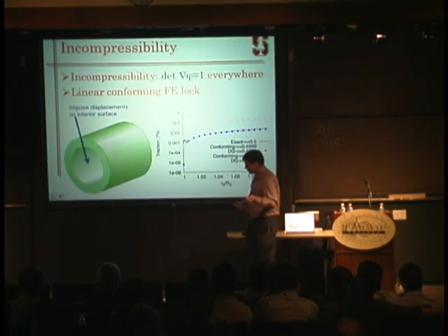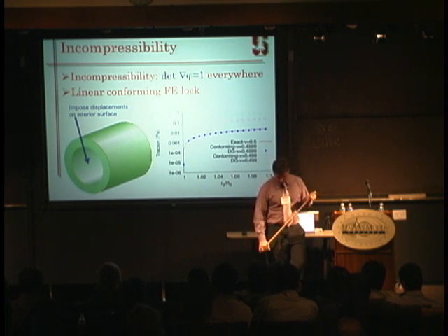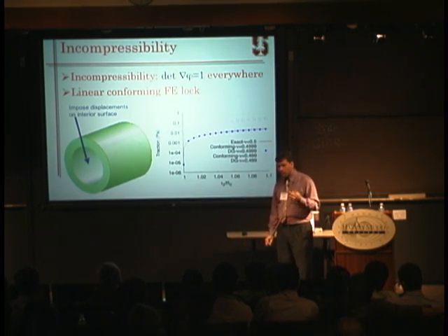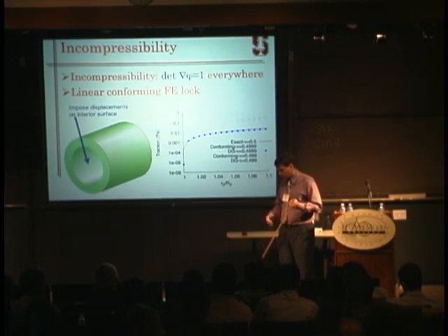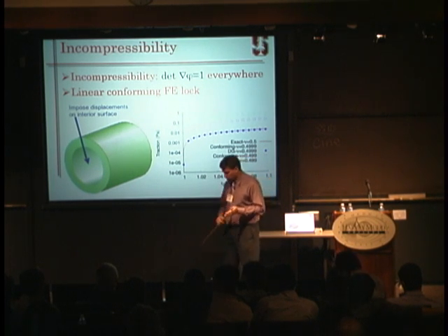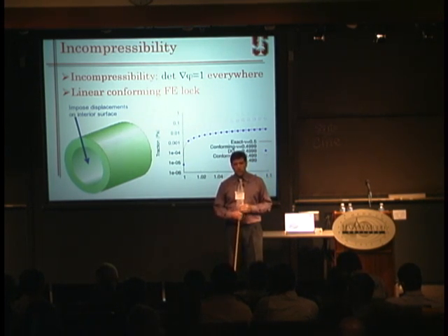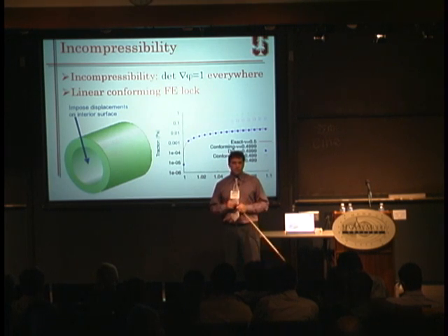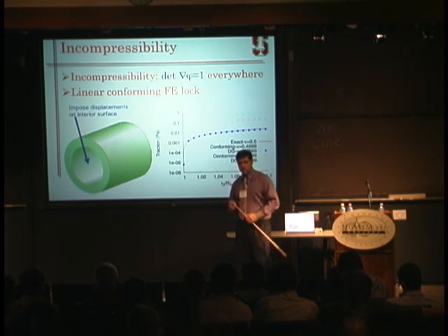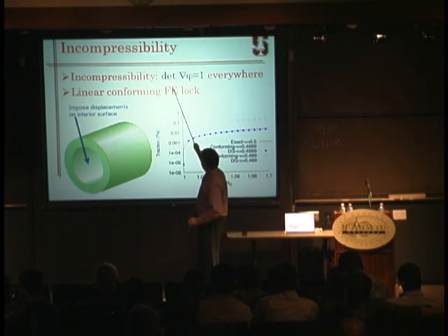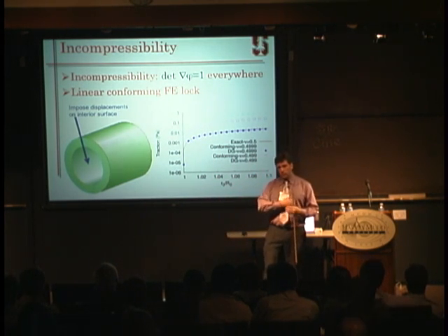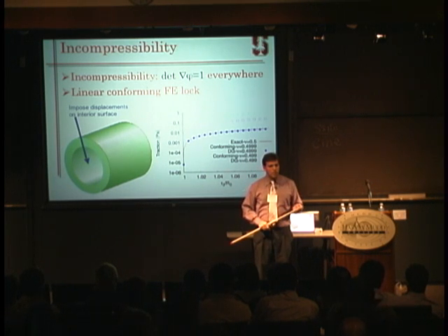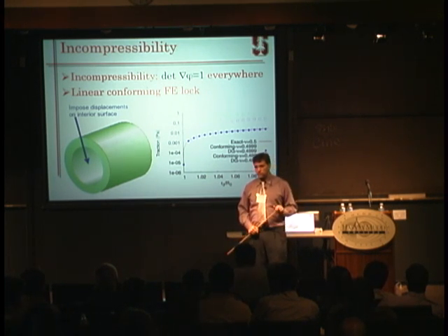Okay, then another example where this formulation has several advantages. One problem that has been pervasive in elasticity, and sometimes in fluids as well, was always to deal with kinematic constraints. For instance, incompressibility. Here in nonlinear elasticity, incompressibility is even worse than in fluid mechanics, because you have a nonlinear constraint that you have to satisfy at every point in your mesh. So if you want to use low-order elements like piecewise linear everywhere, your solution locks, and I will say what that is soon.